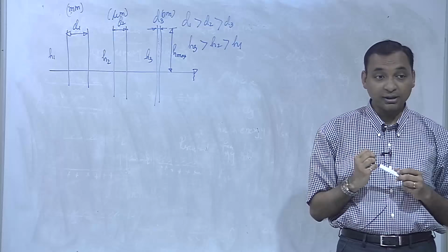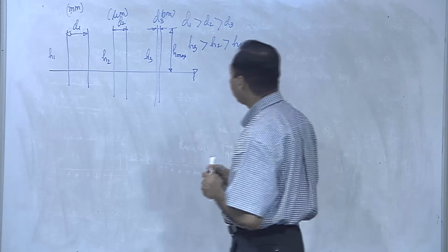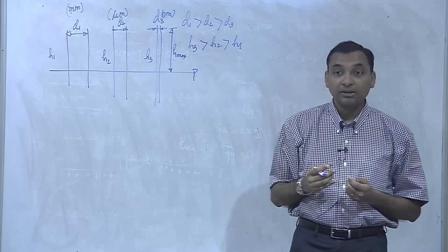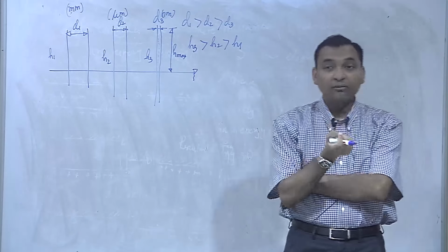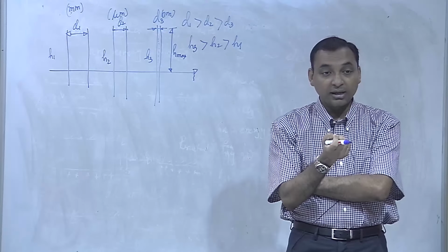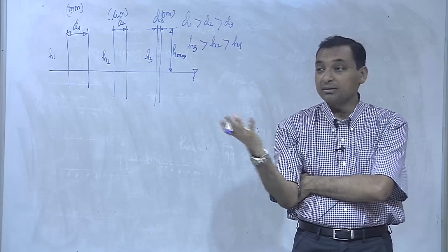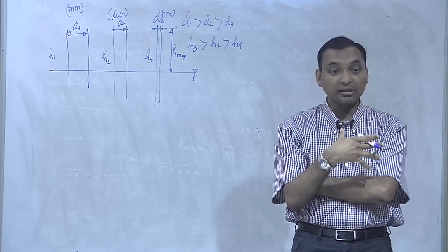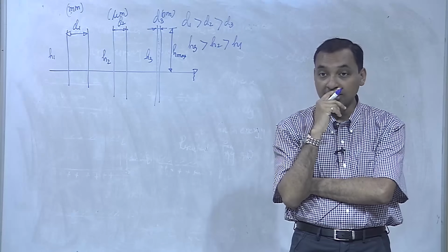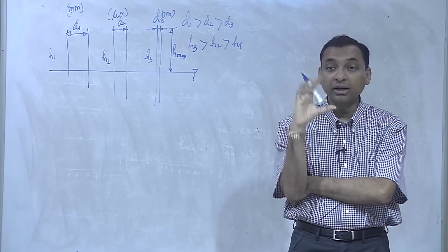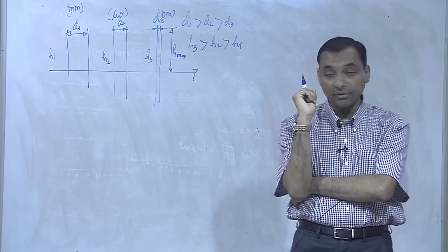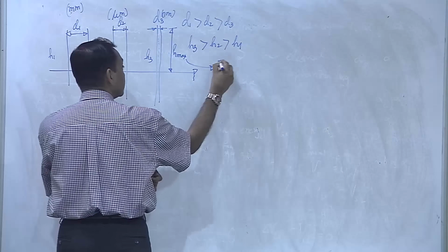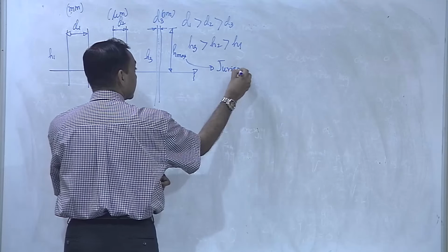So, gravity, right. What are the fundamental forces? One is surface tension. There is gravity, which is pulling it downward, and then there are the viscous forces. So the viscous, the surface tension, and the gravity. The balance of these will create a maximum rise in the capillary. This maximum rise is often referred to as the Jurin height of the capillary.